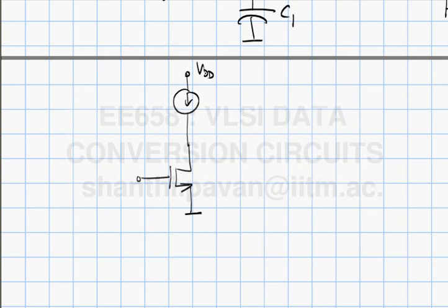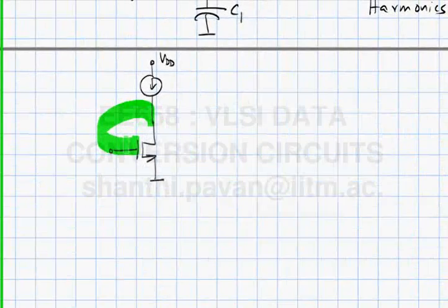While in this circuit it looks as if current is being forced into the drain of a transistor, it's understood that this is going to be sitting in a negative feedback loop, so that there is some feedback from the drain to the gate. All of you are aware that you can't push current into the drain of a transistor. Is that clear to everybody?